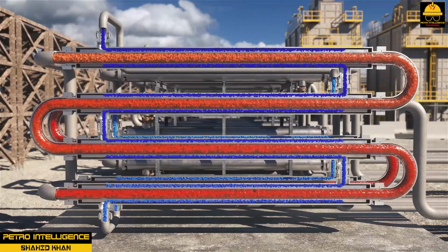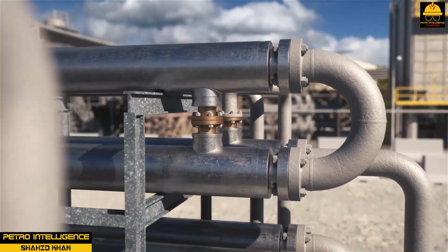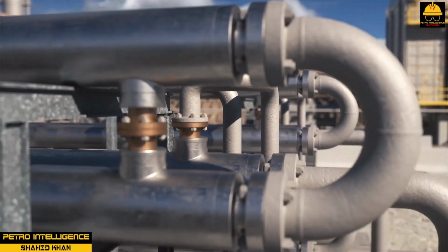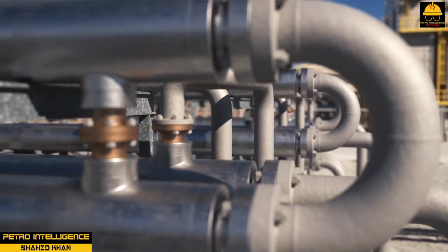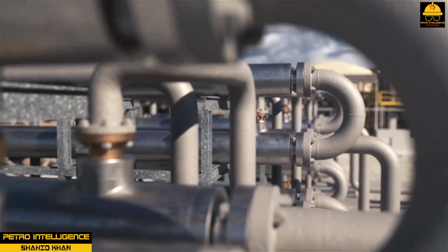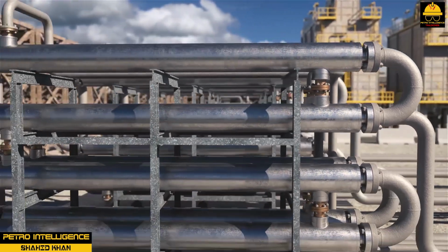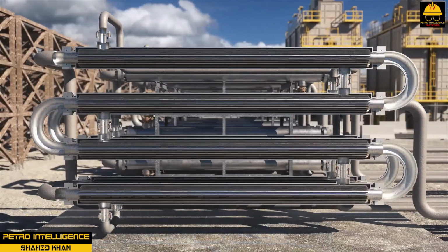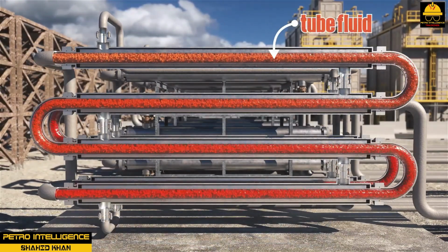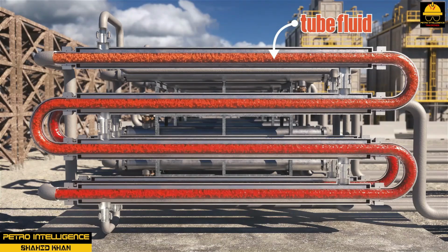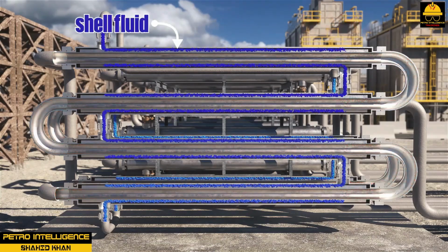Even though the two liquid streams never come into physical contact with each other, the two heat energy streams, cold and hot, do encounter each other. Energy-laced, convective currents mix within each pipe, distributing the heat. In a parallel flow exchanger, the exit temperature of one fluid can only approach the exit temperature of the other fluid.